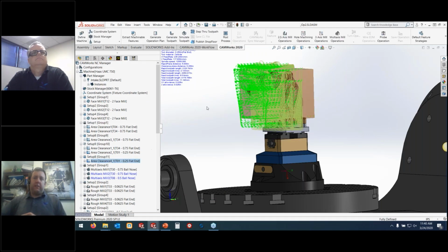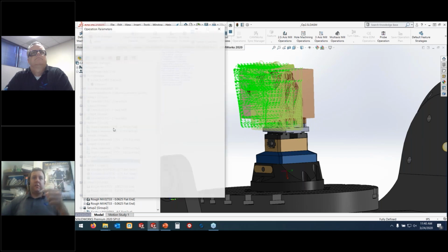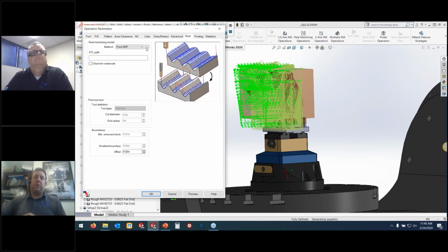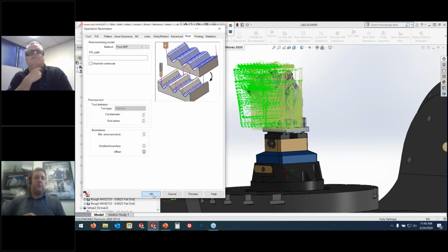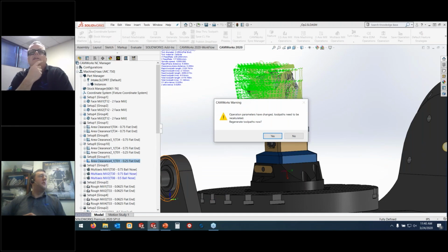And I'm just going to go and cancel the regenerate, just so that I don't waste time waiting for one to generate and kick in. I just like to set them all up and get those 4 generating, and then we'll look at some of the 5-axis stuff as well whilst they're calculating. So we'll go through and set those. I always actually generate each one. I like the idea of waiting.